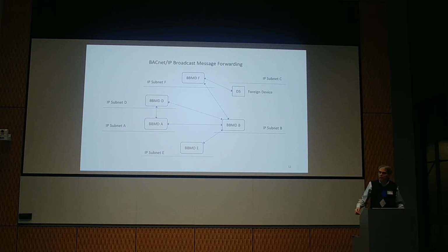So there's a lot of flexibility here, but the problem is that many of the technicians that actually work on these systems don't understand how to architect this kind of BBMD configuration, and in some cases they don't know how to use the engineering tools in order to accomplish a particular architecture. So we run into a lot of problems with BBMDs, especially in big systems like here at BU. Certainly not exclusive to systems as big as this one.